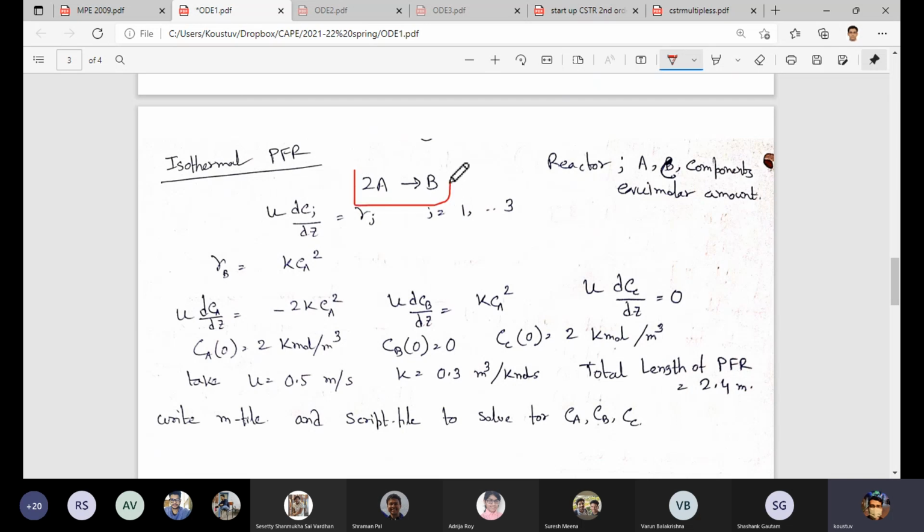It looks more or less a simple example, but it can be similar in nature, and we can have several other equations based on stoichiometries, where we are having some equimolar components, or A and C, where C is basically inert. In several reactions, we actually use inert. In industrially different gas phase reactions, we oftentimes use what we call a diluent or inert, right? So that has several advantages.